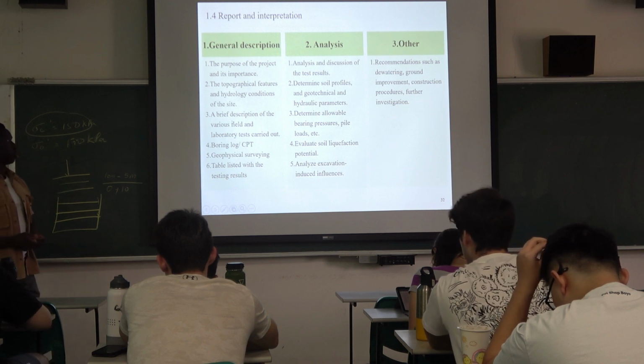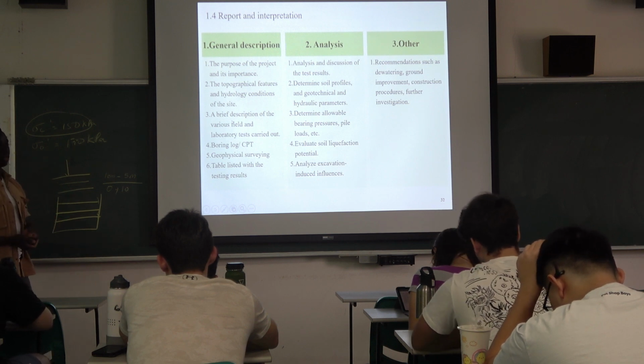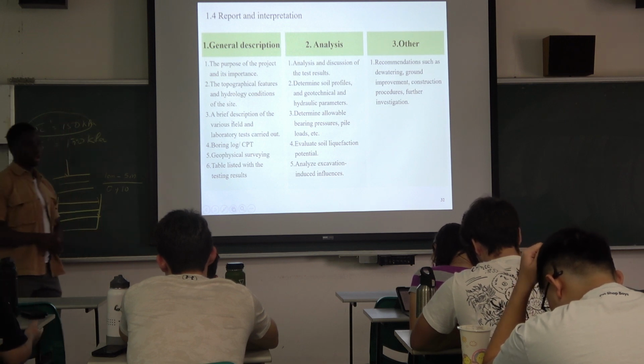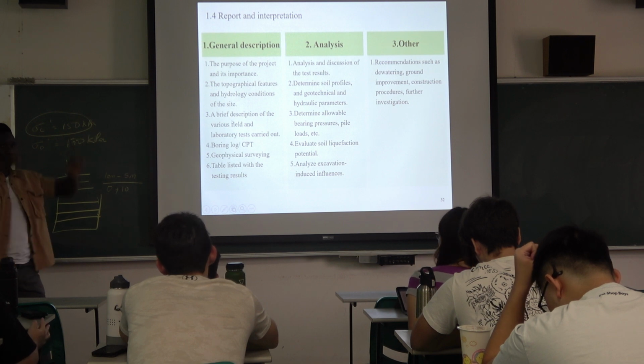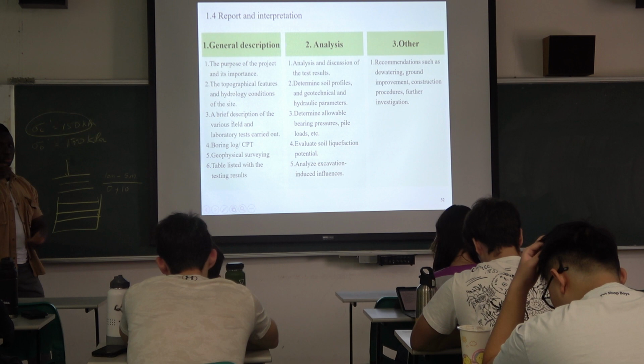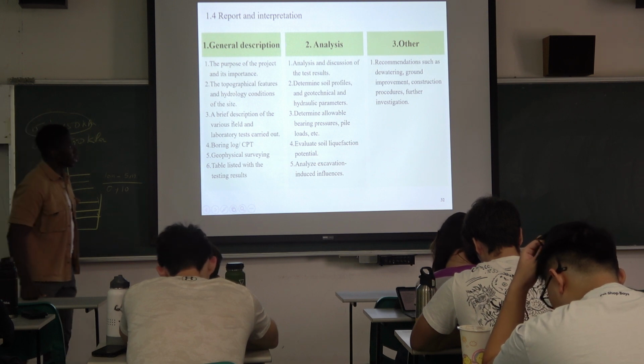Okay, and then the recommendations, so for example, you can make recommendations. For example, if the groundwater level is too high, you can ask them to dewater. So they can seal a certain area of the excavation and then try to dewater, remove the water, before they continue excavating again.